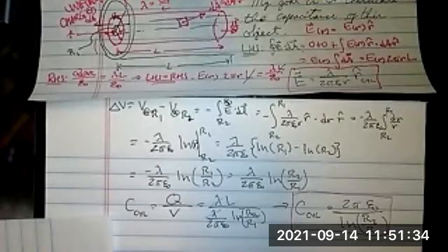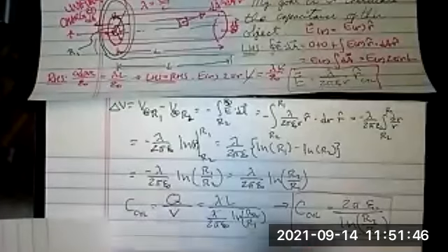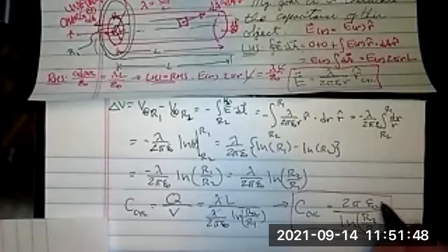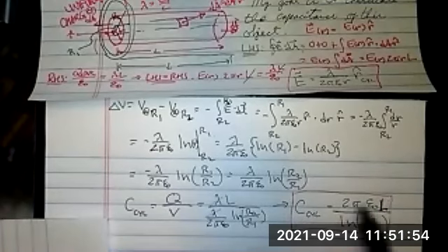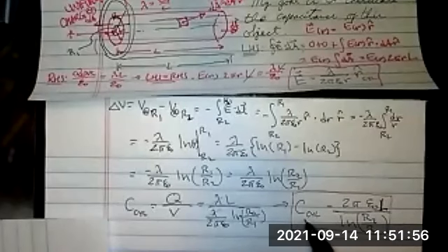But notice it didn't actually put a number by that, right? They didn't label that equation, that C equals 2 pi epsilon naught L. Oh yeah, I left off the L on this, by the way. Everybody make that correction. Make sure you write that L here, okay? Because often it's stated as capacitance per unit length.